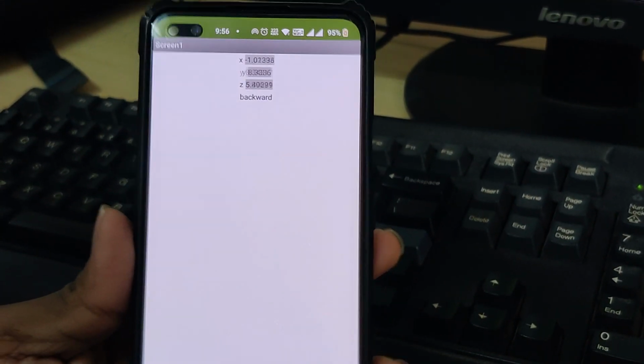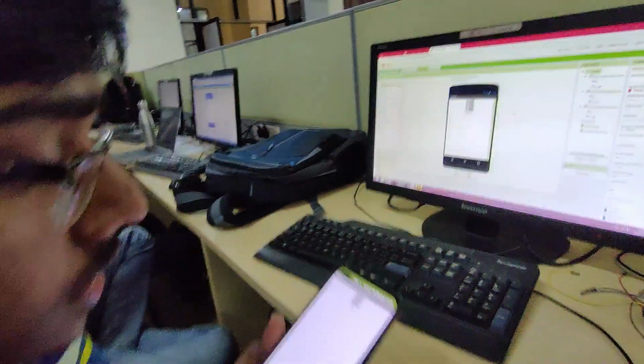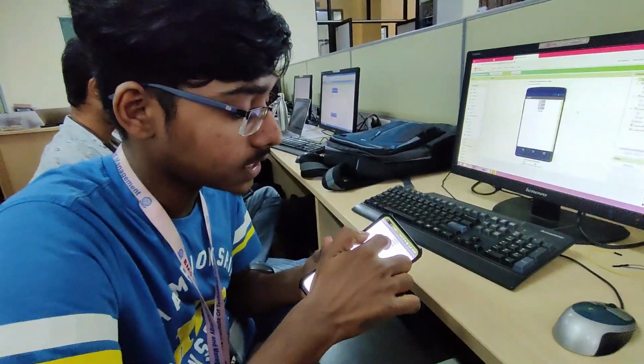Firstly, we required an application which uses the phone sensor to predict the direction of the car, and the sensor which we use is the accelerometer sensor which is present in your smartphone. And the direction must be informed to the PC to which the microcontroller is connected. So for that we would be using Google Firebase as it offers free 5 GB at first.